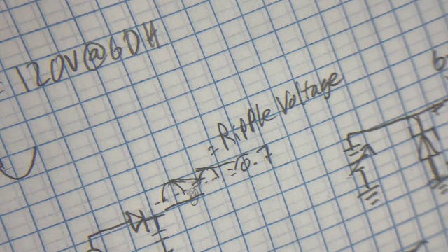And he made a video one time talking about guitar amplifiers and saying that you can double the power of your amplifier, or practically double it, by putting a smaller resistance speaker on there, a smaller impedance speaker.